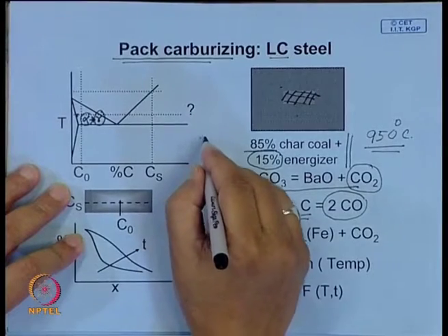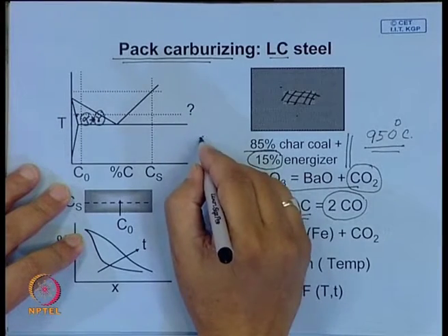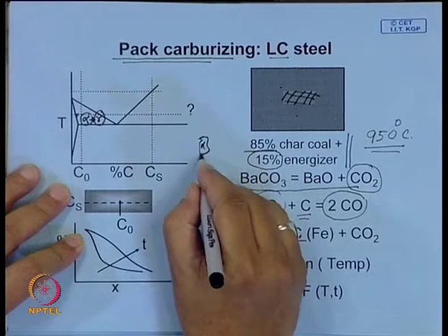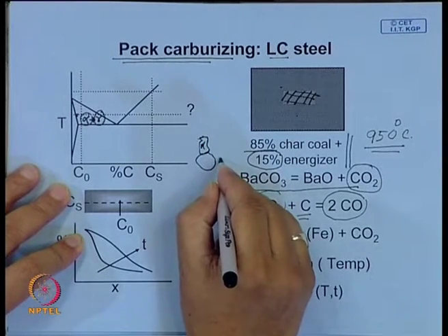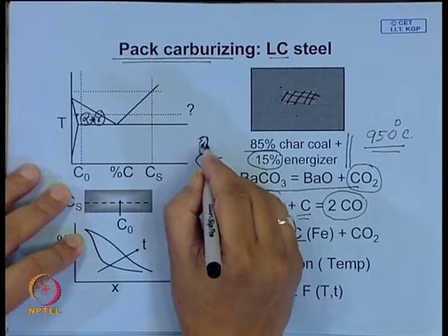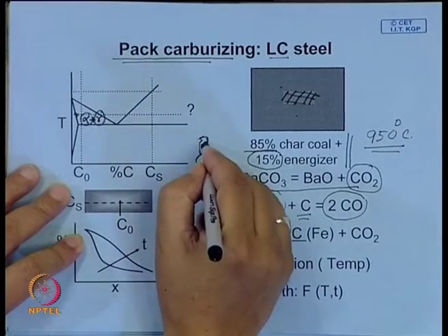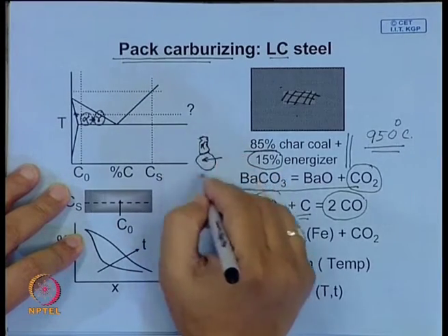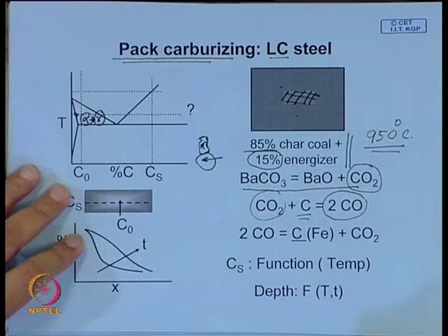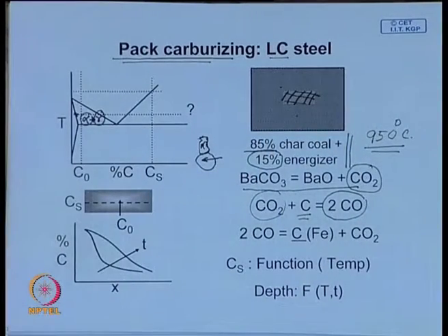So, if you have on the surface a ferrite grain, you also have an austenite grain. You will find the carbon will diffuse more here and very little over here, because ferrite solubility is very little. So, here again the problem will be that carbon distribution is not likely to be uniform in the structure. So, this is a problem.